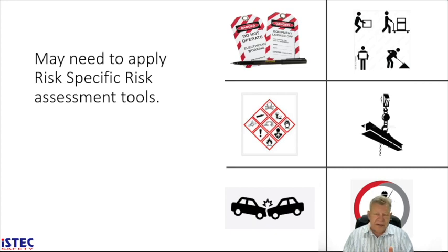When we look at lifting, we need to identify that there are lifting plans. We normally limit lifts by trained people to about 5 tons, but bigger than that, we normally get a qualified rigger. Before they lift, they do a specific risk assessment, a lifting plan. That lifting plan looks at the weight, the distance, the size of the crane they require, the size of the slings, and any objects in the area. So it is a very specific tool related to lifting incidents.